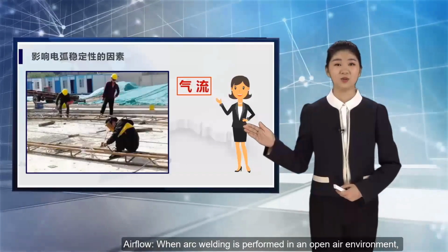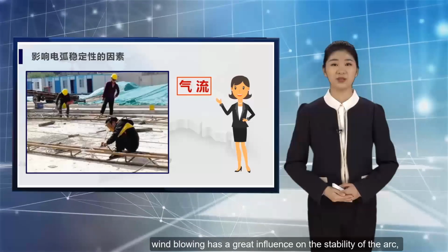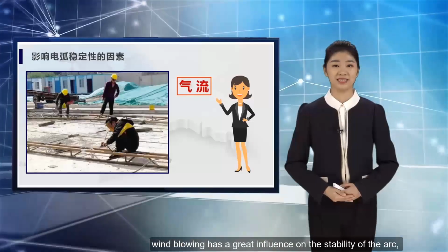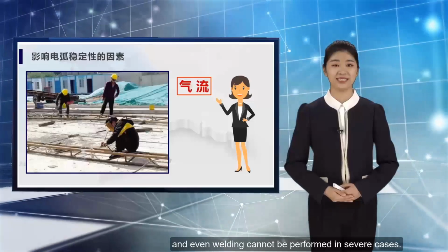Airflow. When arc welding is performed in an open-air environment, wind blowing has a great influence on the stability of the arc, and even welding cannot be performed in severe cases.